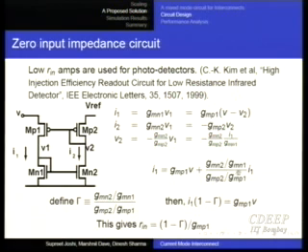Okay? So now you define this ratio to be some gamma. Then what do we get? I1 into 1 minus gamma. We take it to this side. So I1 into 1 minus gamma is GMP1 V, and finally therefore our input impedance, which is V divided by I1, is 1 minus gamma divided by GMP1. If I can make gamma equal to 1, then I've got 0.